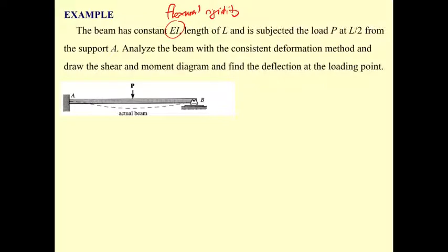Constant, okay, with the length of L, subject to the force P at it with the length as before, and we use the consistent deformation to analyze this. And by doing this, we mostly set B_y as the redundant. Okay, we are going to solve for the unknown force. After we have all the reactions, we draw the shear diagram, moment diagram, and find the deflection at the loading